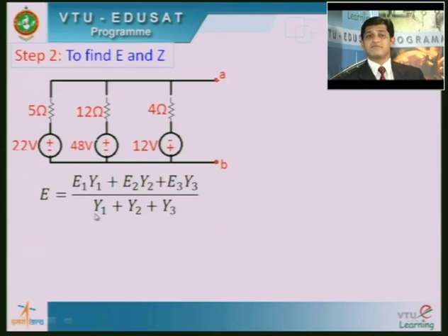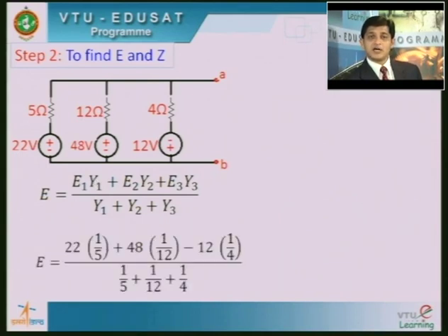That means we have written the equation in terms of the admittance, not the impedance. This is another thing you need to consider. You just cannot take this 5 and substitute it in place of Y1. What is Y1? Y1 is 1 by Z1, so Y1 needs to be substituted as 1 by Z1. Get that point? With those substitutions, your equation would look like this.